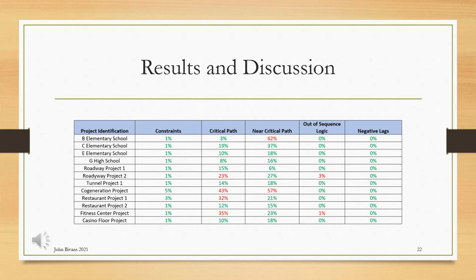With respect to project density, of the 4 projects that failed to meet the critical path percentage, 3 projects had a project density below 150 total activities. The average delay incurred within these 3 projects was 51.3 calendar days, well above the average of 26 calendar days. Although this could be construed as an indication of increasing impact, the amount of critical path activities will always increase as the number of activities in a schedule decreases. As a result, this metric is inconclusive in relation to project density.